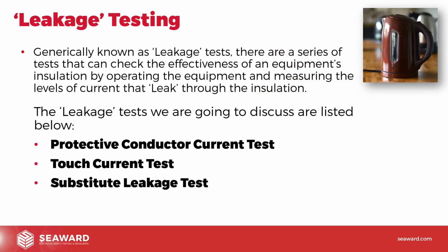So, leakage testing. The name leakage testing covers a wide range of tests. Generically known as leakage tests, there are a series of tests that can check the effectiveness of an equipment's insulation by operating the equipment and measuring the levels of current that leak, for want of a better term, through the insulation. The leakage tests we're going to discuss today are listed below.